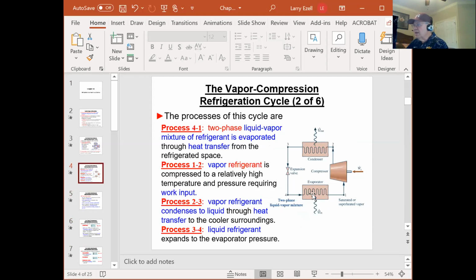The same m dot, of course, flows throughout: m dot times H1 minus H4. Now, going into the compressor, if we want to use plus as work going in, because that's what the arrow shows, we know that state 2 is a higher energy state because it's compressed up to higher temperature and higher pressure. So the work for the compressor to jive with the arrow is m dot times H2 minus H1.